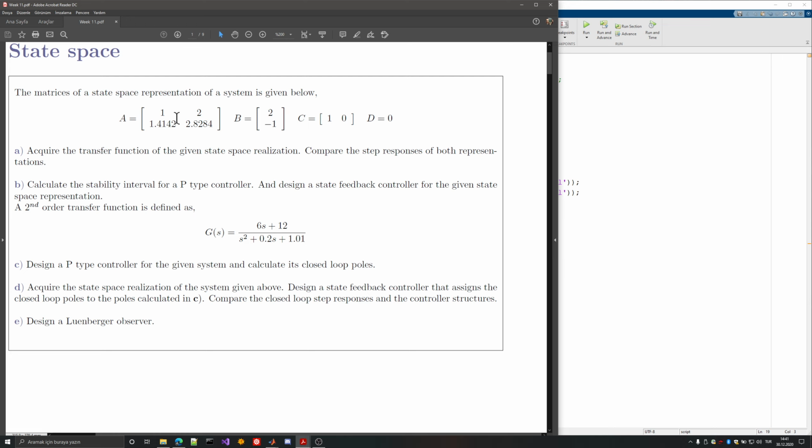And if the structure is well designed, it should give you basically the states, or your estimates should approach the states, and you will then use a linear combination of these estimates and feed that back to the system.